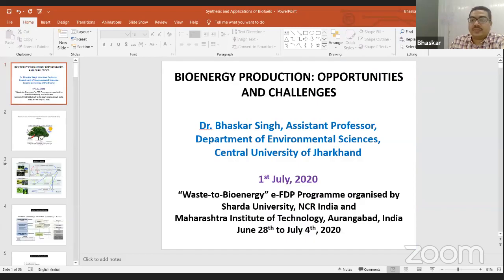Yes. So the first question is, which pre-treatment method can be preferred for bioenergy generation from biomass? See, the pre-treatment method will depend upon the feedstock which is being taken. For example, for bioethanol, if the feedstock is lignocellulosic biomass, the pre-treatment can be acidic, using HCl or H2SO4. It can be alkali also, NaOH.